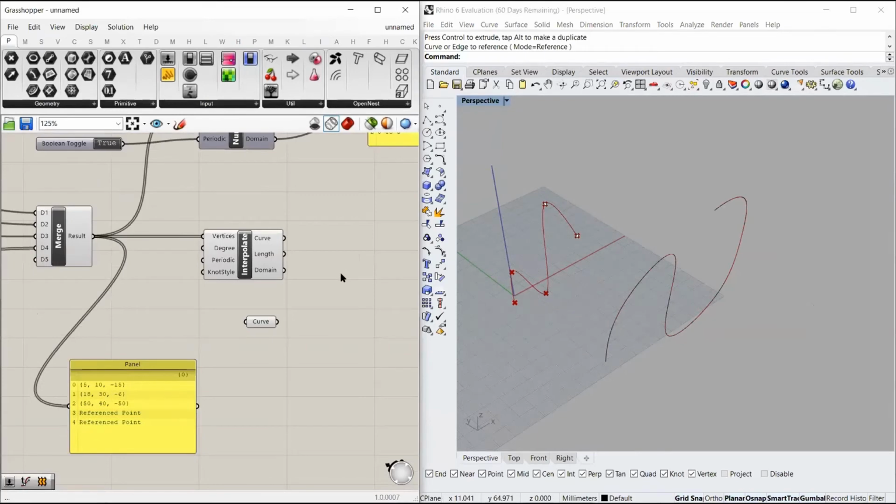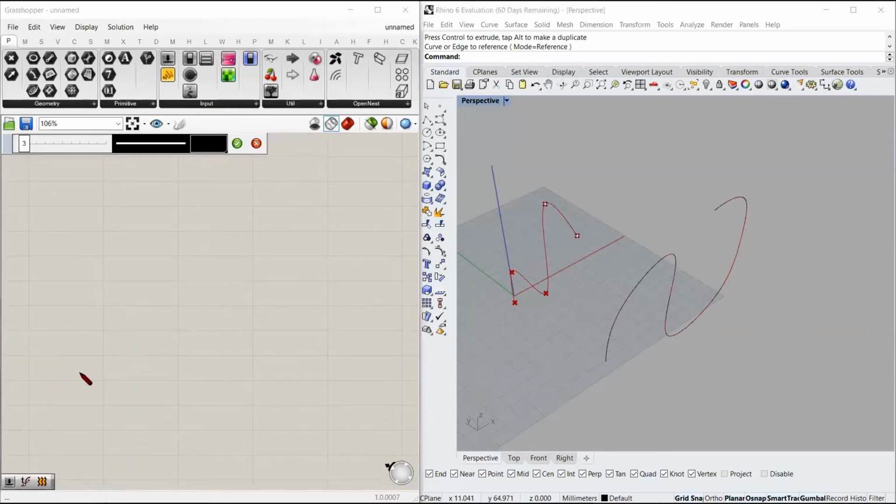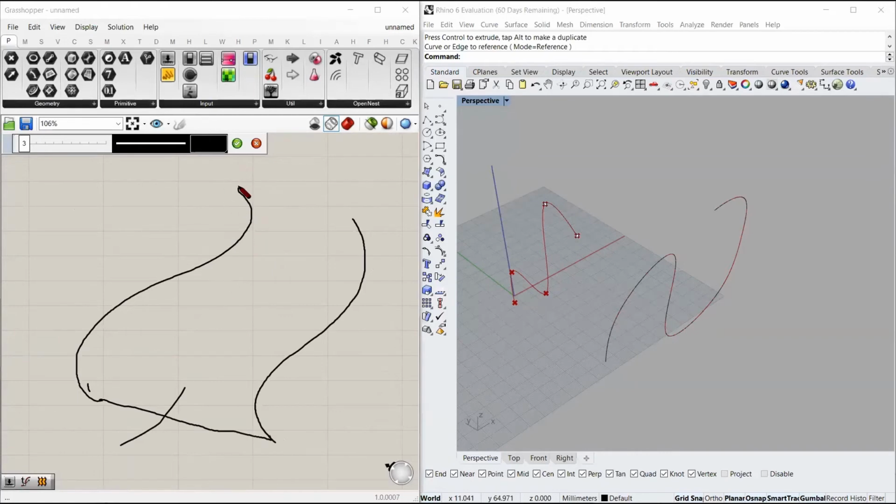So there is a component called loft. So what loft does, basically, suppose you have this surface, you have this another surface, and if you want to loft this curve from this curve, what loft does, it matches the start point with the start point and the end point to the end point and creates many points in between these start and end points in a particular order, and it makes a smooth surface along this.